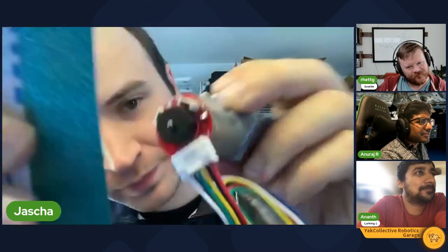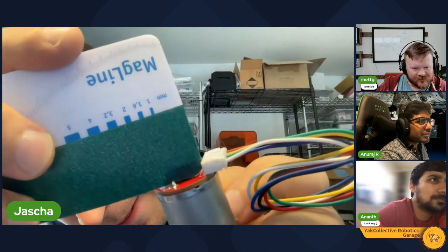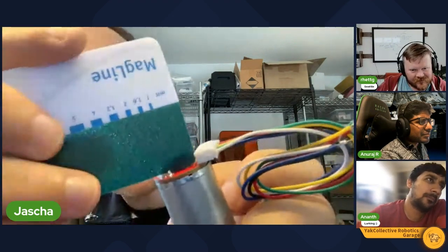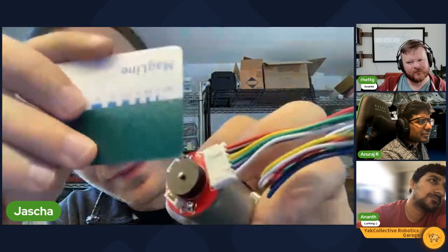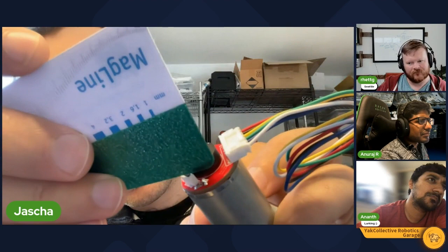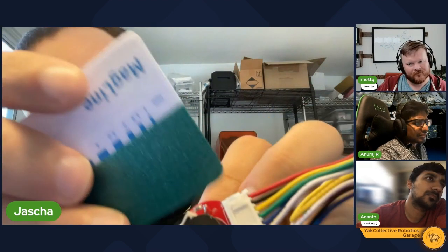Maybe if I go this way, it's easier to see. See how there's like multiple little segments. So the point is, this little cylinder has, I think, 64 magnetic poles. We could count them with the film if we actually were to sit here and measure it. But this is actually a little encoder. You have a multi-pole magnet and then two Hall encoders, and that's it. So anyway, that's just something to look for when you are buying these motors.